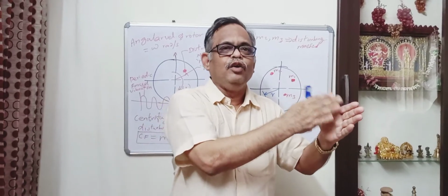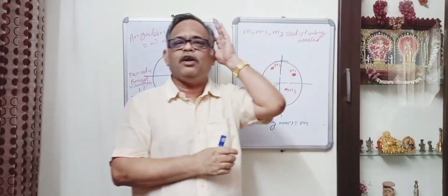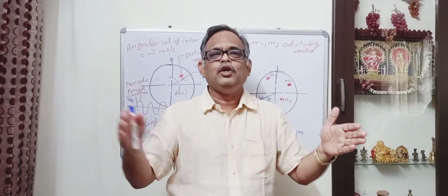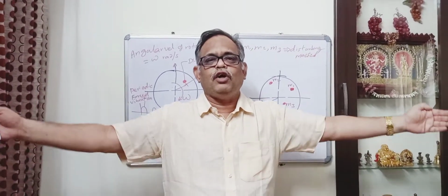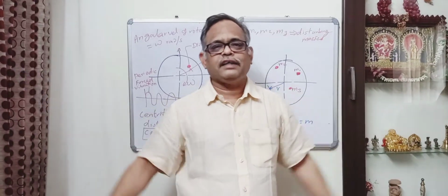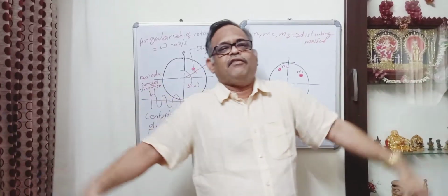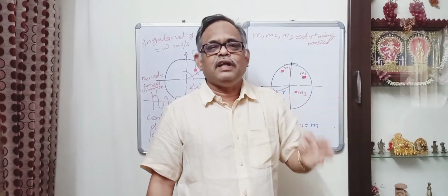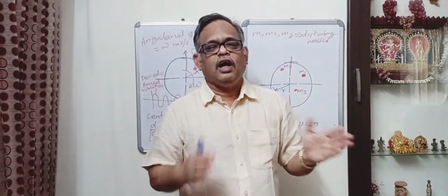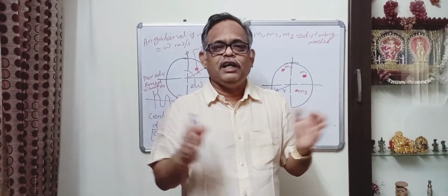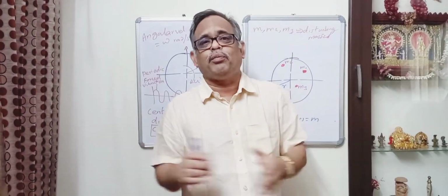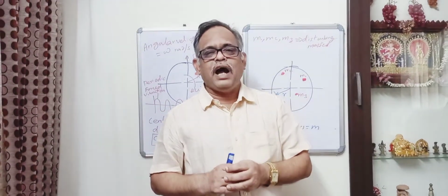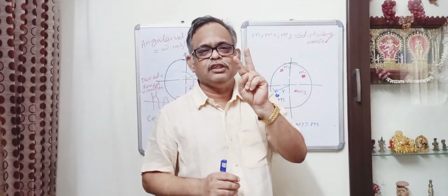Take the case of a steam turbine, where there are so many rows of blades placed over a long shaft, and in such cases, in each row of blades, there can be some disturbing mass, and so several disturbing masses in several planes are possible, right?